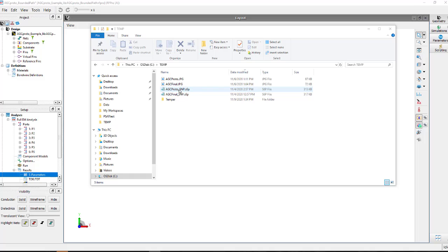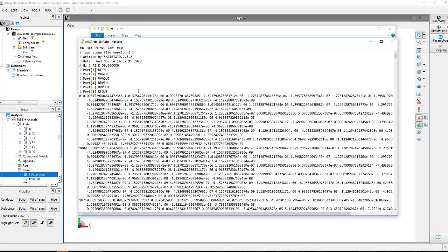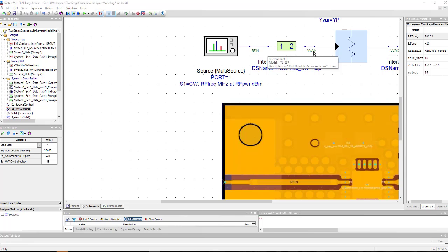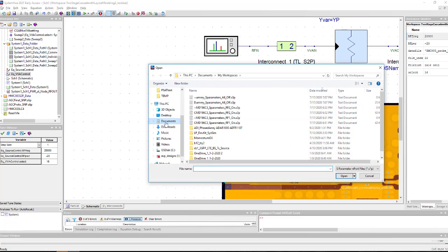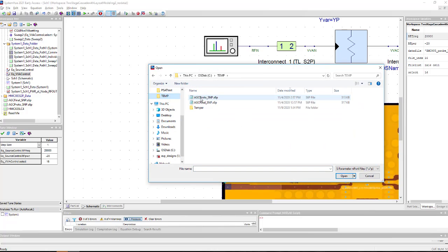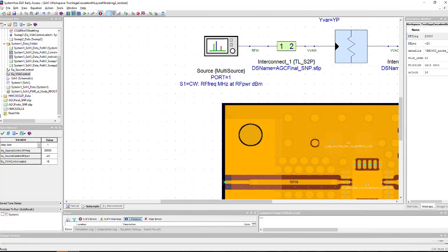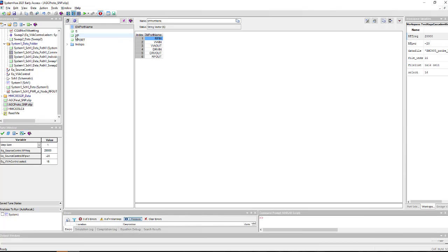And I went ahead and opened the file. This is the prototype here. And just made a few quick little edits. You can see up in the port declaration area here, I went ahead and made sure that the names here were the same names that I was using as shown here, across the signal chain. So then I imported that data, file, import, sdata, and I browsed to that file location and imported my data into the dataset directory here. You can see it again, along with the names, those different EM port names.